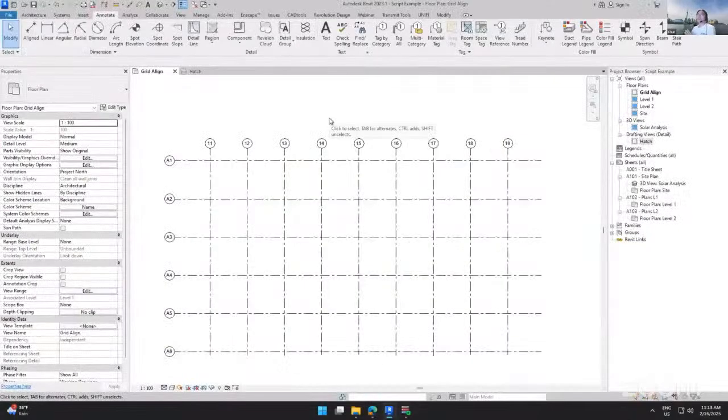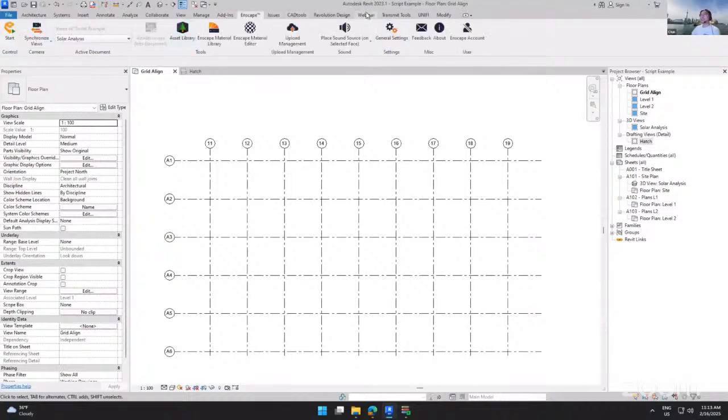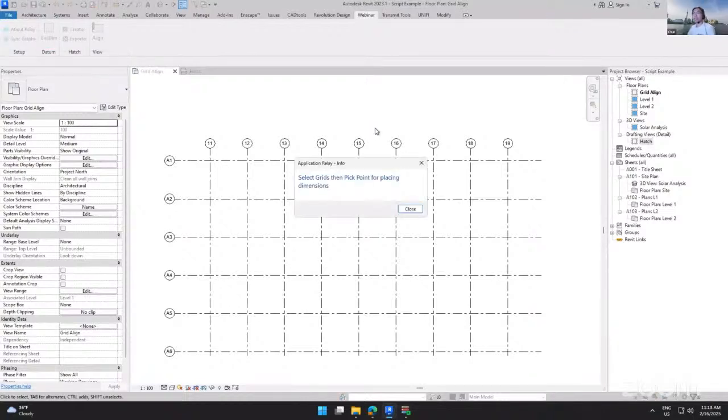So I prepared a Revit model, and I use Relay for Revit to show some of the scripts that I made in the past. What it helps me do is, right now this one is a button, just like other add-ons, but behind it is actually a Dynamo script. As you can see, the path is below. So when I just click on it, it will run.